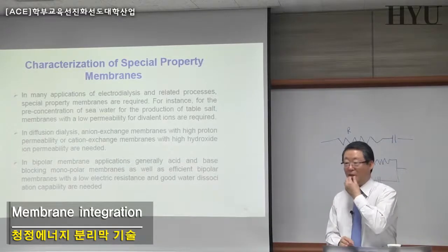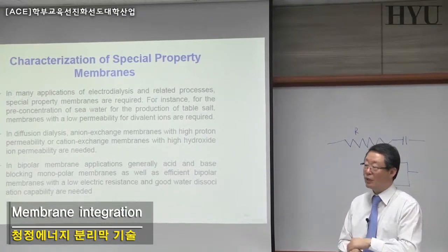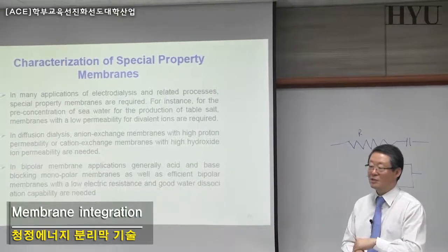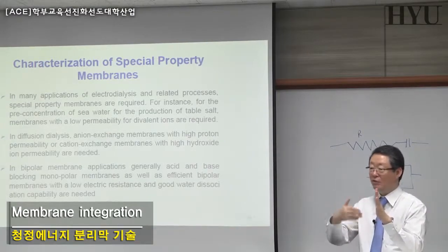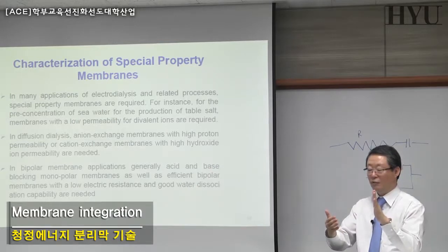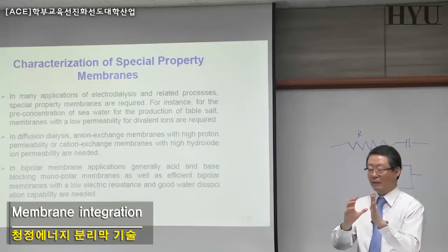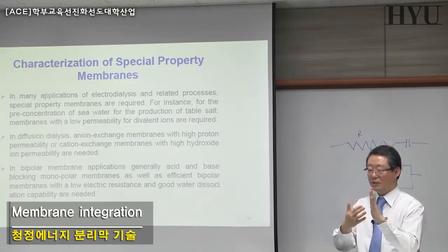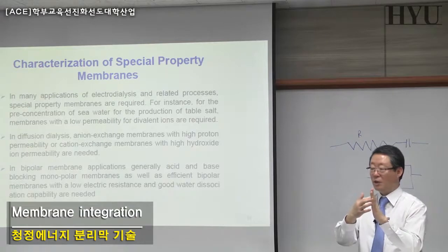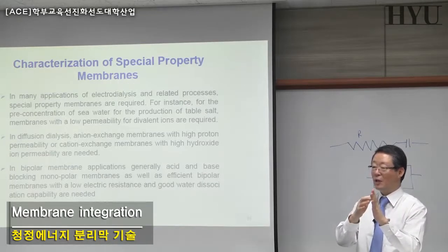Anyway, we are making crystals, particularly sodium chloride crystals, using what we call the membrane crystallizer. You have a pre-concentrated solution in the feed, and if you drag the water through this membrane, the feed will become much more concentrated and start to aggregate on the surface of the membrane, and could grow on the surface because you already formed the nuclei.